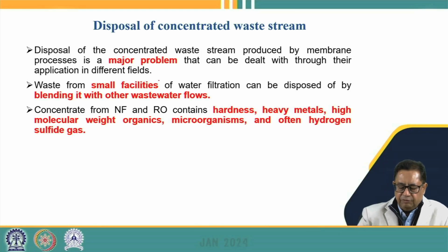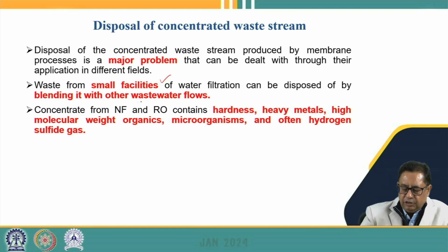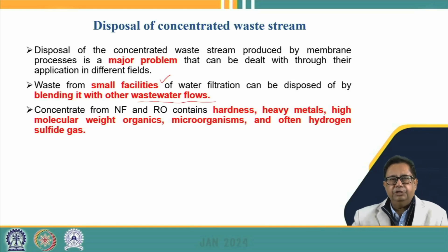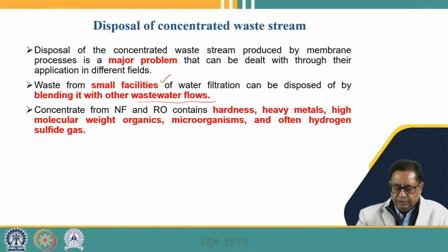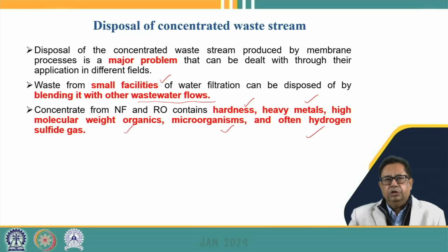For example, if we have small facilities where water filtration is taking place, the concentrate can be blended with the wastewater flows, where it can be treated further. The nanofiltration and RO concentrates may contain a high amount of hardness, heavy metals, high molecular weight organics, and microorganisms, and they may also contain hydrogen sulfide gases, etc. Whatever we have removed from the water or wastewater is concentrated, and these things now appear in a concentrated form.